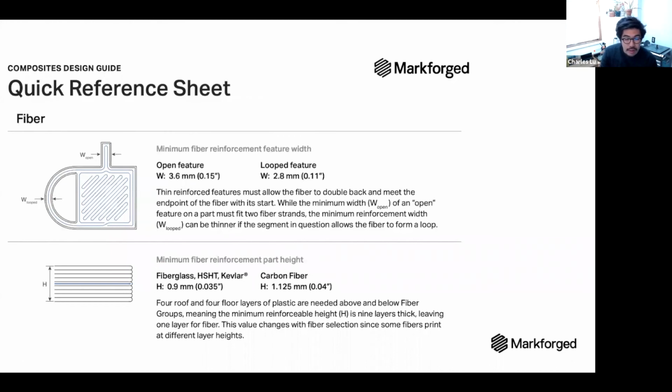Ignore infill and just take into account onyx. And yeah, I would say just count the infill as air. If you really wanted to count it, you have a thicker section, take what the volume percentage is. We actually list what the percentage is and multiply the strength by that fraction. But what I've realized in doing some of these calculations is that the onyx barely contributes to the base strength once you start adding fiber, because this fiber is just so much stiffer and stronger that the onyx hardly adds anything to the calculation.